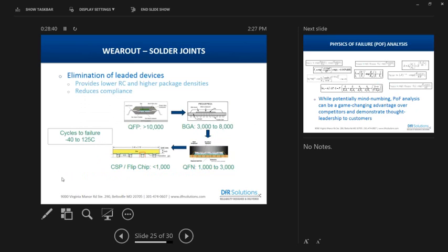And we talked about solder. I've mentioned solder joints already. The reason solder joints are now more in the forefront as far as failure issues is because the industry has moved away, well, hasn't moved totally away, but people want to move away from your gull wing leaded devices. And this is primarily due to cost. You get rid of that extra piece of metal and you have a cheaper part. Unfortunately, that gull wing is a compliance adder. It adds flexibility to the part. It takes in some of the CTE mismatch between the part and the board, and therefore you have a longer life.